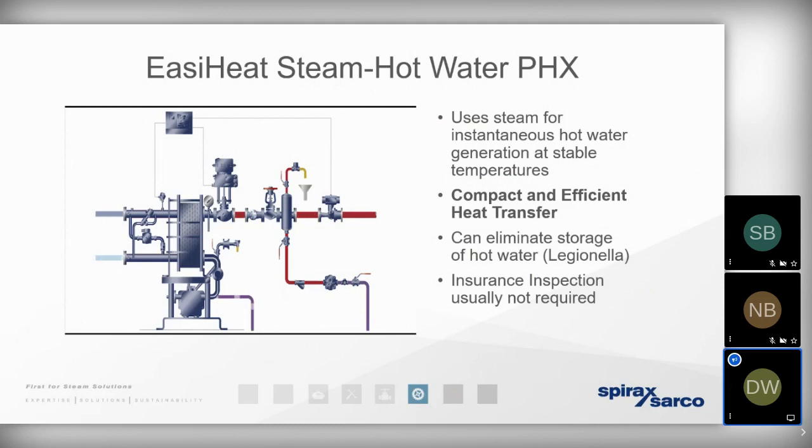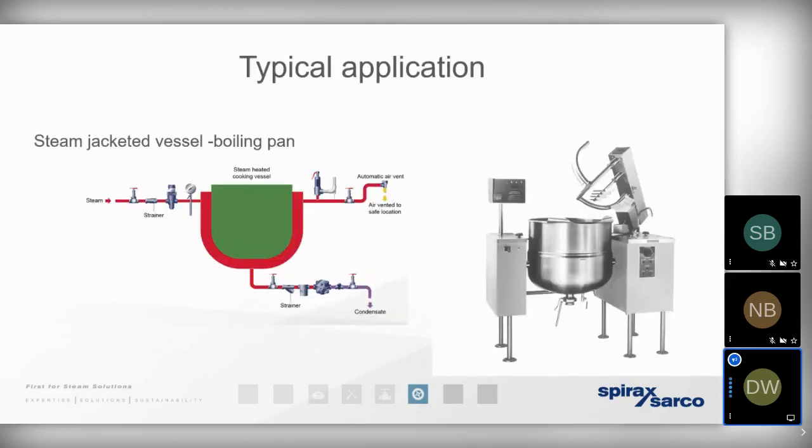So typical steam using applications. In the food and beverage industry, we could be looking at a jacketed vessel. We know it's important to keep the steam dry and clean. We know it's important to vent the air away using that thermostatic air vent.